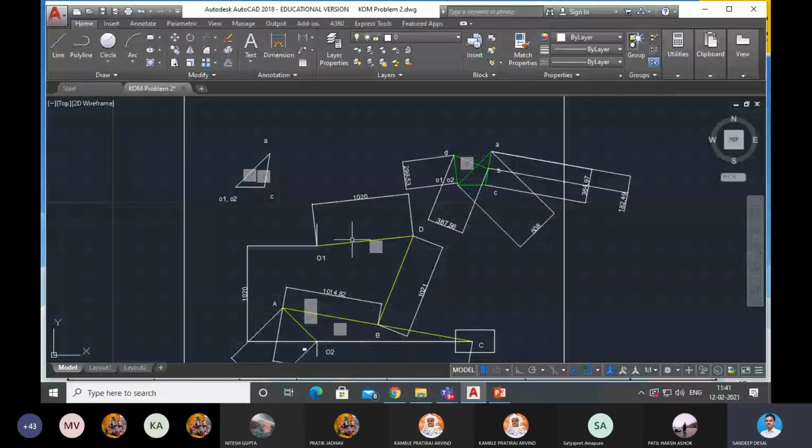Now what is remaining is this link and this link. There are two more links remaining whose velocity is to be represented with vectors. Which are the two links remaining? O1D, very good. And BD. So which link should we do first? O1D. Okay, but right now, see, we have not identified point B on link AC. There is one more point on link AC, no?